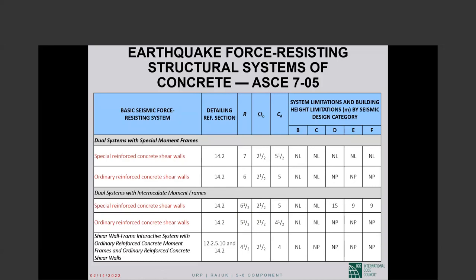It never pays. No, it's not B, it's D, as in dog. If it is D, then you are not even allowed this option. You have to go for special shear walls. Not permitted. This part of the table you should look at. I was thinking B. In D, that is not an option.